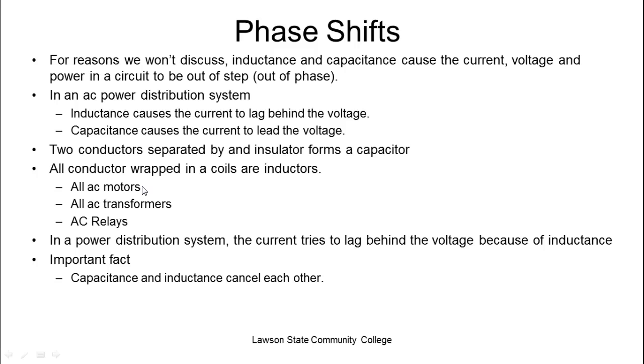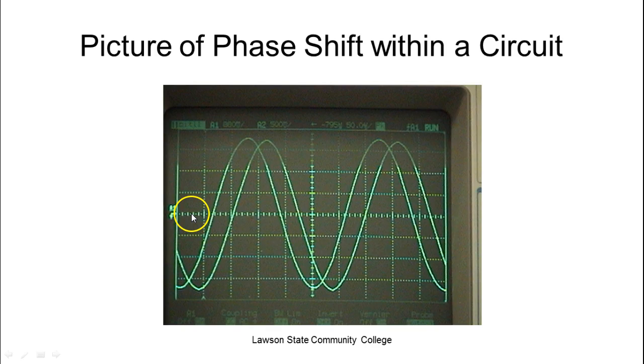Single-phase motors are going to have a start winding which has inductance in it or has capacitance, which creates the phase shift. Inductive motors are referred to as split-phase motors, and these are for low starting torque applications like fans. Capacitive motors have a lot better starting torque because they can create a greater phase shift. And what this means is most of your motors that actually run something like compressors are going to be capacitive motors or capacitive start motors.